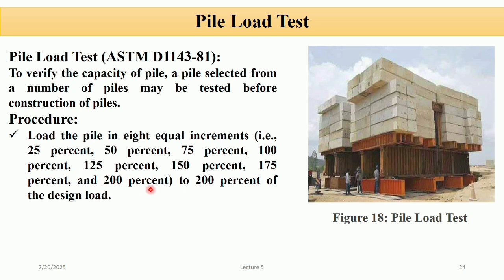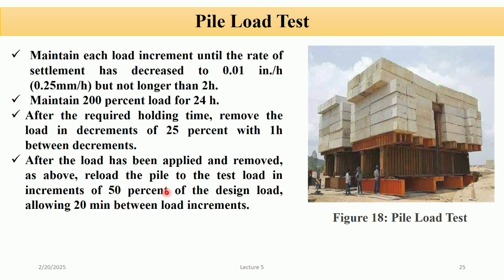Then when we reach 200% of the design load, we have to maintain this load on the pile for 24 hours. After that, we have to unload the pile in decrements of 25% with 1 hour between decrements. Then after the load has been applied and removed, we have to reload the pile to test the load in increments of 50%, and maintain this load on the pile for 20 minutes, and then we apply 100% of the design load.